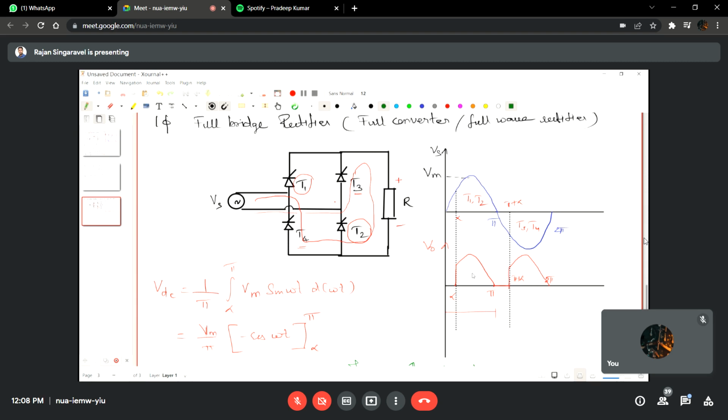And if every component is a diode, it will automatically rectify the sinusoidal supply whenever the zero crossing occurs. So if you do such an operation, the average output voltage will be maximum when alpha is equal to 0. So when alpha is increased, the output voltage is decreased, proportional to the alpha value and proportional to this formula. And the output voltage will never become negative at any point of the cycle, since the load is considered as completely resistive.